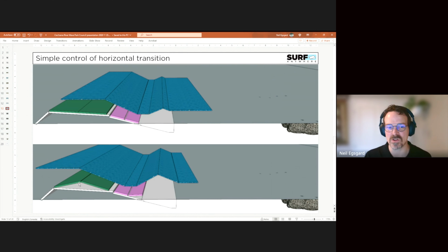There will be issues with sediment underneath here, very likely, and the idea is to do an inspection once a year, use the other parts to divert it, because this is a few sections wide. So when we do the inspections once a year, the idea is to be able to direct the water flow away from where we want to inspect. We're not trying to dewater, so the water will still be there, it just will be moving very, very slowly. Then you can go in and inspect it with divers in order to make sure everything's going okay.